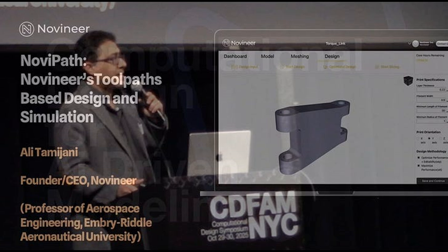The conventional way, which is the first one, right? This is the conventional way. You can find it in any slicer, Cura, this is the way you do it, right? So there are two conventional ways. The first one is unidirectional, right? Whatever angle, but unidirectional. The second, in different layers, you can have different directions, but in each layer, unidirectional. The second way is boundary offset.